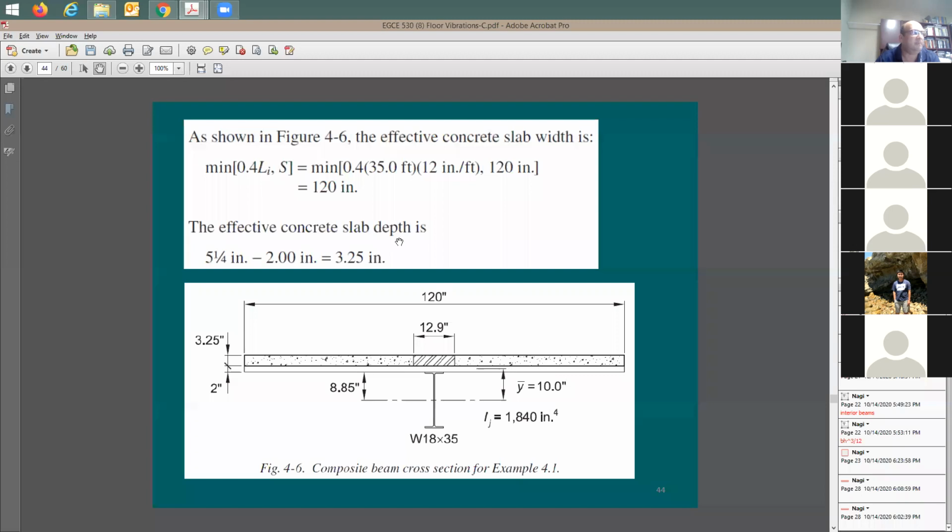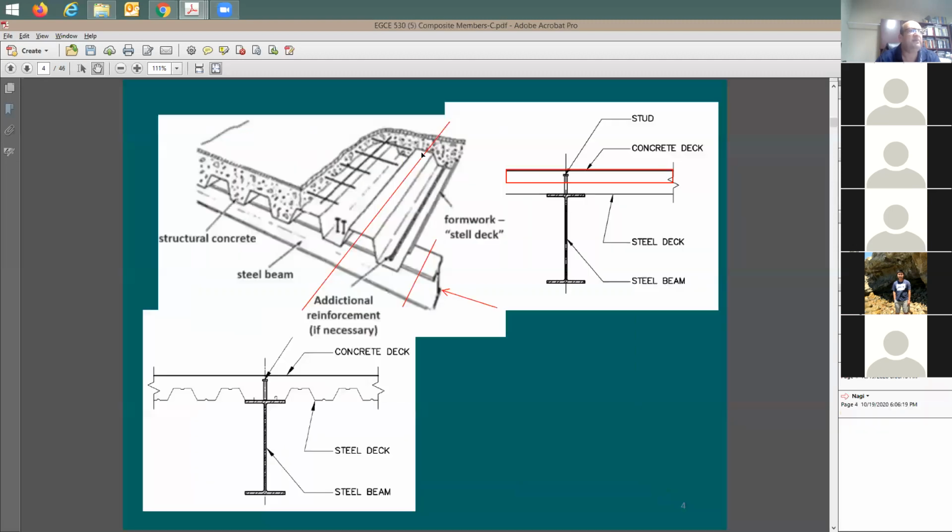Because you can just simply take a section right here, and this is gonna be the critical section that you need to consider. Someone's gonna say, why don't you cut the section right here? I said, oh, but in this case, the moment of inertia is gonna be big. But actually, when you take a section through the beam here, you're going to see this can be the critical section, and this is going to be controlling your analysis. And this one here doesn't make any sense to consider.